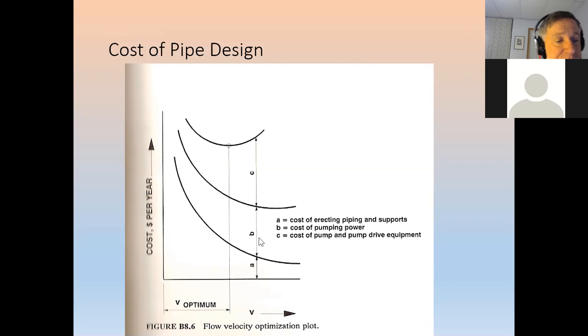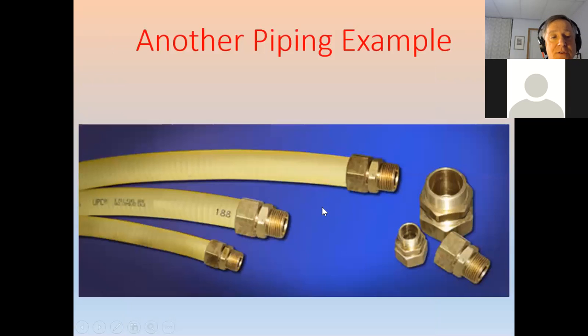So there's an optimization you can go through where you look at, okay, what's the best size to move things efficiently? And this could be a moving target. There's an economics in here because you're saying small pipes are efficient and they're easy to install and easy to make and use less materials, et cetera, but they require more pumping pressure for the life of them.